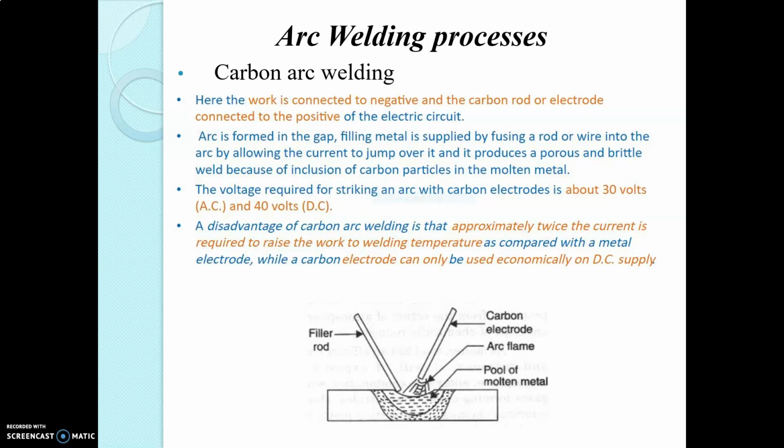In heavy welds, a filler rod is melted by the arc and deposited in the weld. Twin carbon arc welding is very similar to gas welding, in which the heat is generated above the work and is played upon it. The difference between the two is in the source of the heat and the atmosphere around the work.